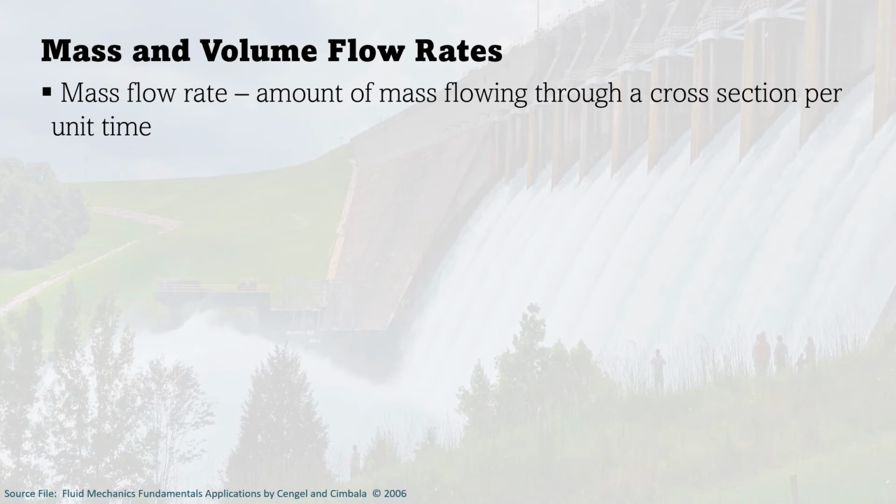For control volumes, on the other hand, mass can cross the boundaries. So say for example, for a turbine, a mass of water can cross the boundary of the turbine. It will not be stuck in the turbine. When mass is stuck in a system, say for example a piston cylinder arrangement wherein a fixed amount of gas is stuck there, that is a closed system. But here, since the mass can cross the boundary, it's considered a control volume.